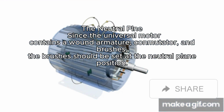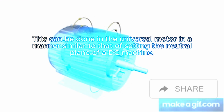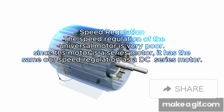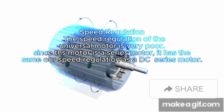Neutral plane: the universal motor contains a wound armature, commutator, and brushes. The brushes should be set at the neutral plane position. This can be done in the universal motor in a manner similar to that of setting the neutral plane of a DC machine. Speed regulation of the universal motor is very poor. Since this motor is a series motor, it has the same poor speed regulation as a DC series motor.